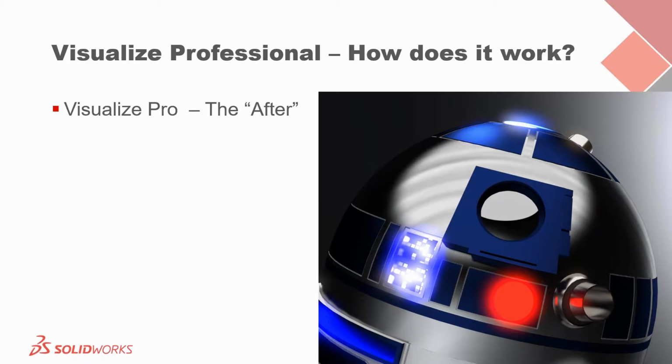I was able to take advantage of the bloom option for my emissive lighting. I added some directional lights, and I also added some spotlights, along with tweaking the perspective settings to really bring the image to life, right? I think that one looks pretty good. We're going to jump into Visualize in a second, and I'm going to show you a few things that I utilized to create this and how easy it was.